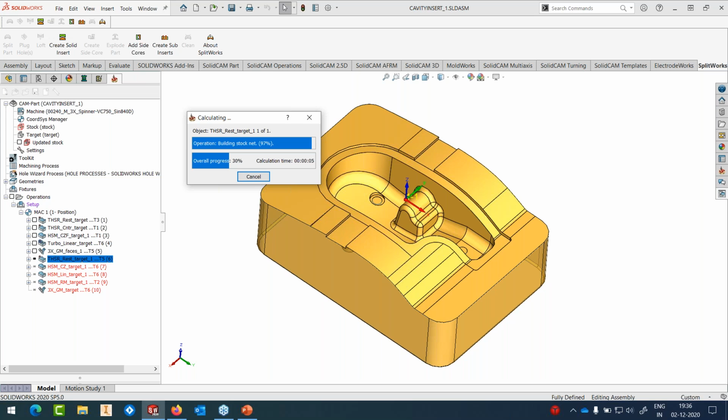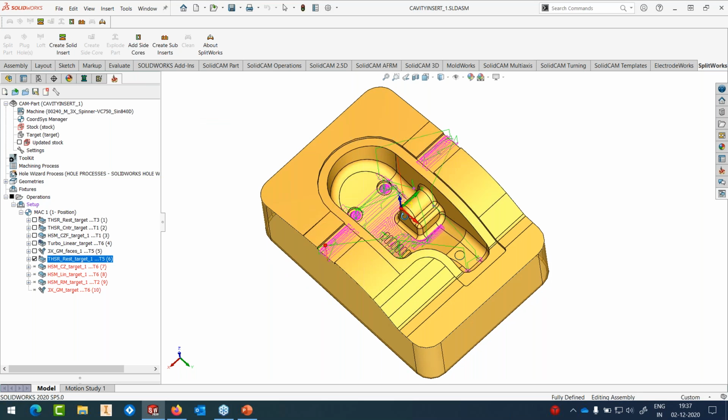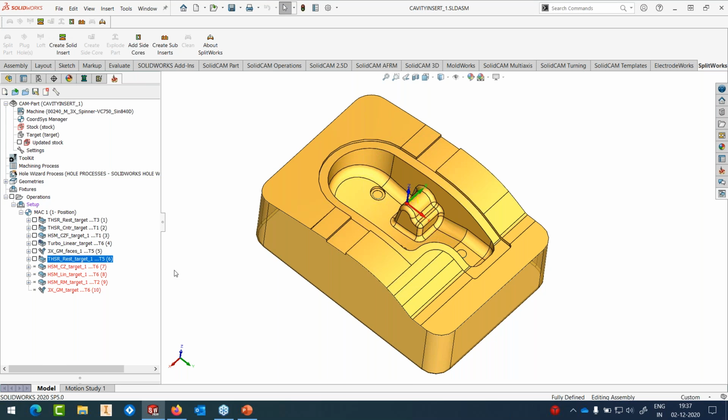And all these calculations are happening actually live. Okay, 25 seconds. It's calculated. It's done. We can now safely assume that the part is ready for running the finishing operation. We can put a semi-finishing if we need. Basically, semi-finishing is nothing but finishing itself with a smaller offset.